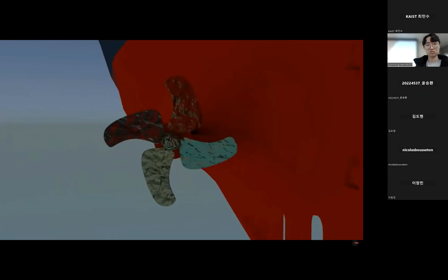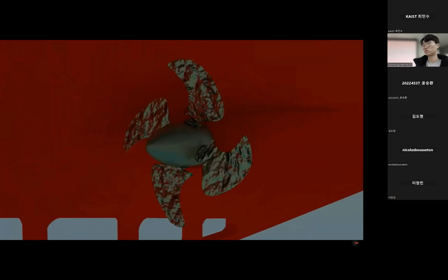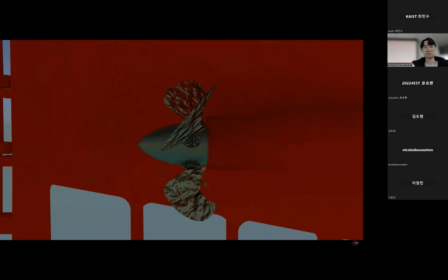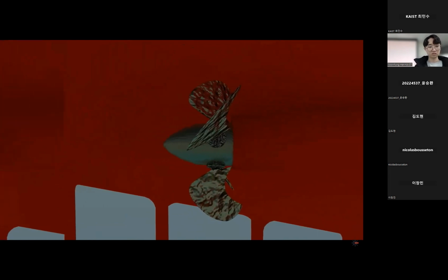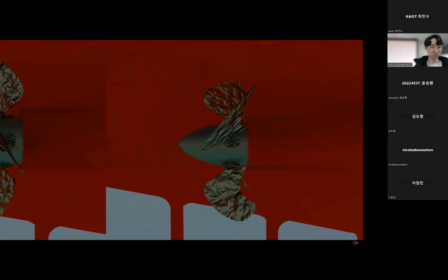The controllable pitch propeller just needs to alter its pitch to be pointing the other way. If we stop it again, you can see the alteration becomes a lot clearer. The shallow angle generates lesser stern thrust, but you can increase it by altering the blades even further. One thing to just compare quickly is the path that the water is directed down. Going astern, you can see the shape of the blade is less efficient than it was when going ahead. This is why ships' astern power is sometimes up to 50% less than for the same pitch ahead.